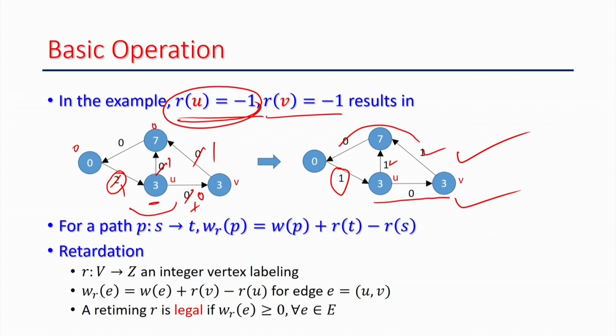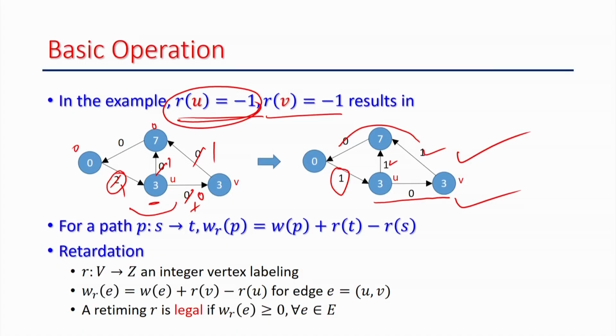So, we consider a variable R for each register, and we try to find out some set of inequalities or constraints which will be satisfied by this R, okay, that we are going to discuss. And then we try to solve those particular set of inequalities using the shortest path problem, which will give you the value. Okay. This is the overall approach. So, what is the set of constraints now?